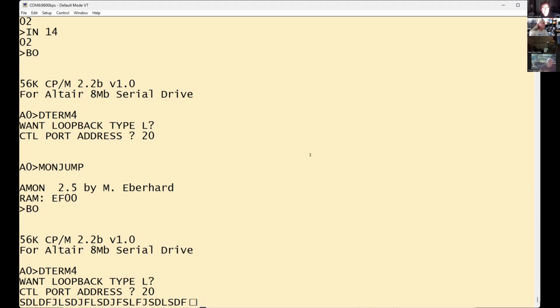Okay, now let's see. See, now I've got it connected to the DCE port to the modem, and I can't see anything showing up on the modem. No lights move on the modem. So you're typing on this little program here. Yeah. Then that's a cable problem. It's a modem problem or a cable problem, because it works fine on your Altair.